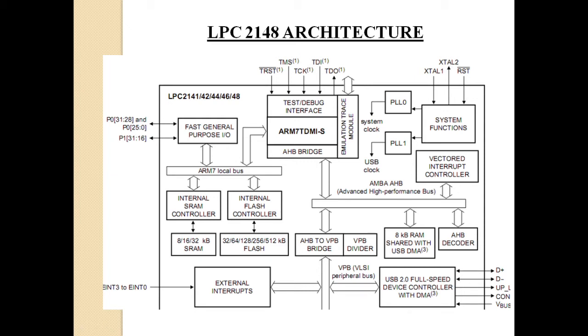Whenever it is getting a small frequency signal, the crystal will start vibrating in its fundamental frequency, or whatever you want to call it, in the desired frequency. So if you are taking a 12 megahertz crystal, and it is getting a low frequency clock from the controller, that crystal will start vibrating at 12 megahertz. So it will generate an accurate 12 megahertz clock in this line.